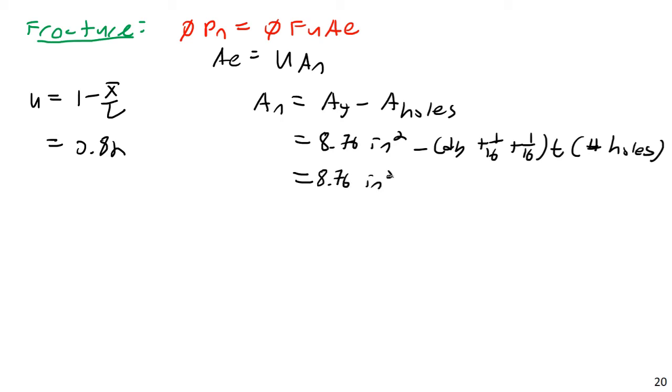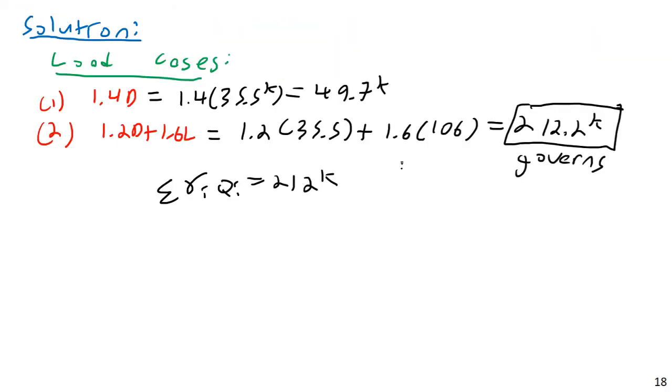Then, as a reminder, the first 1/16 is due to the extra space needed for the bolt hole, and the second 1/16 is due to damage that occurs in the underlying plate as you're drilling the hole. But if you combine those together, that comes to 1/8 inch, minus 7/8. So the diameter of the bolt over here was 7/8 inch.